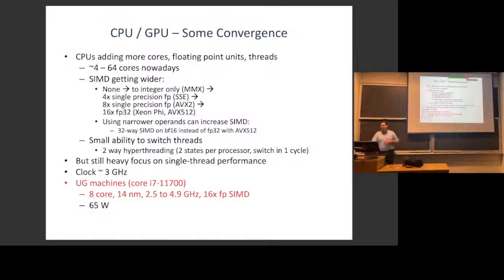Yeah, because these are power consumption constrained. So this processor can go up to 4.9 gigahertz, so its timing will permit that. It generally cranks its voltage up to make that happen. And if you're using only one core or maybe 2 cores, you can get that. If you're using all 8 cores, and especially if you start using this very wide SIMD, so you've done a great job as a programmer, you're getting lots of throughput, you do now lose some of your clock frequency.